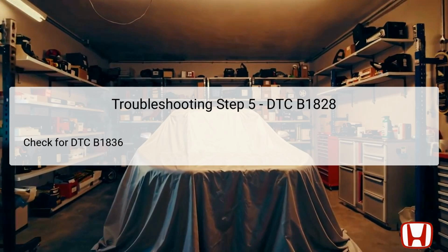Next, check for the presence of DTC B1836 by using the HDS to scan for additional codes. The presence of this code may indicate a related issue that could either compound or clarify the situation regarding the recline motor error. If DTC B1836 is indicated, it's essential to follow the troubleshooting guidelines specific to that code to ascertain the nature of the problem.